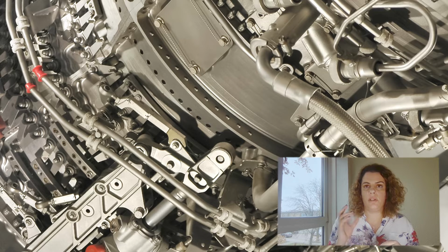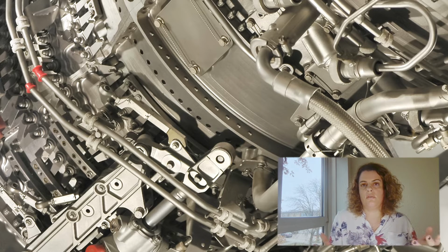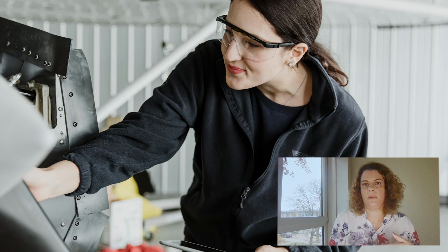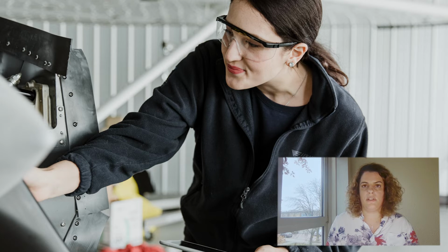Some parts are what we call the life-limited parts, the LLP. And these parts, when they reach a certain limit of time, they need to be scrapped. They need to be taken away and replaced by a new one. Okay? Even if there's no signs of actual very complex deterioration. Where are the parts repaired? Some parts are repaired at specialized shops, other than the airline shop, and other parts can be repaired in-house in the airline facilities.